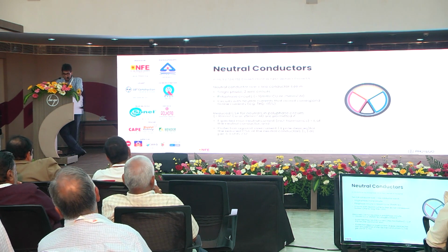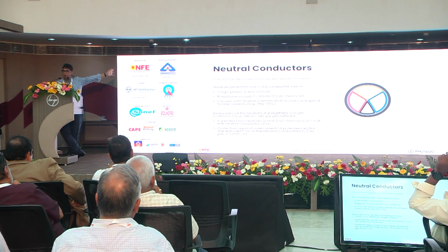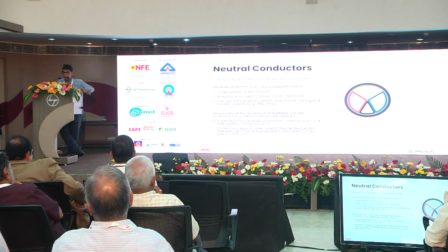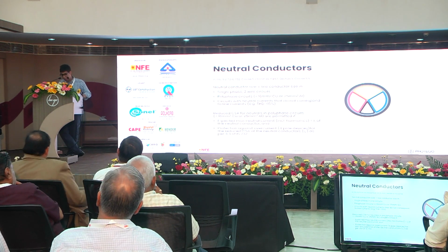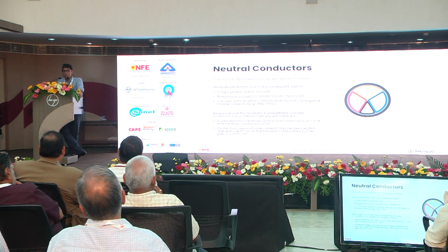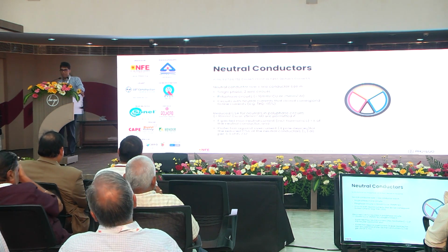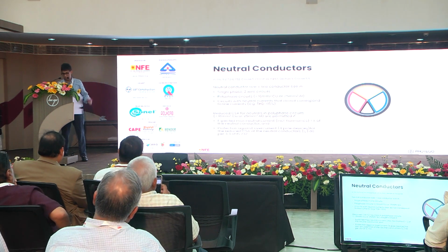Now neutral conductors. How many of you have seen a 3.5 core cable? Heard of them at least? They're very common. People say neutral doesn't carry any current, let's use 3.5 core cable. The truth is, maybe. In a lot of foreign countries, these are being phased out now. So where can you use a reduced cross-sectional area for neutral? You absolutely cannot do it if it is a single phase circuit because the neutral current is going to be the same as the line current.